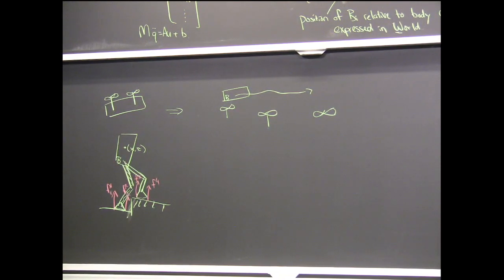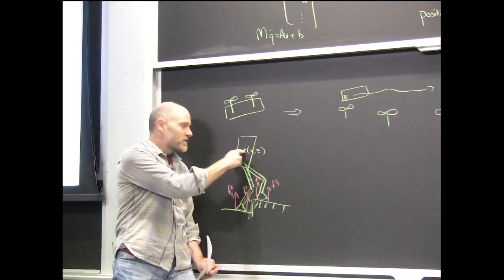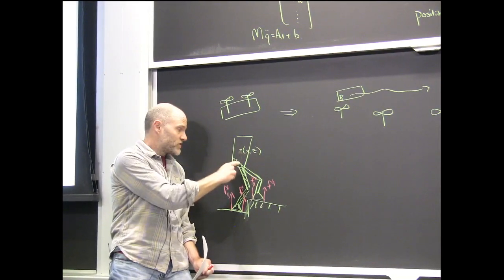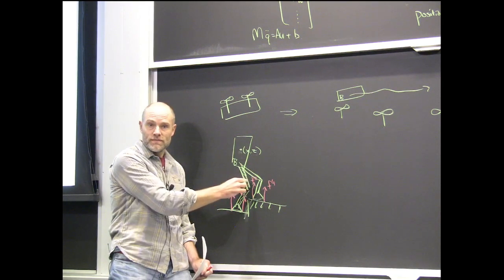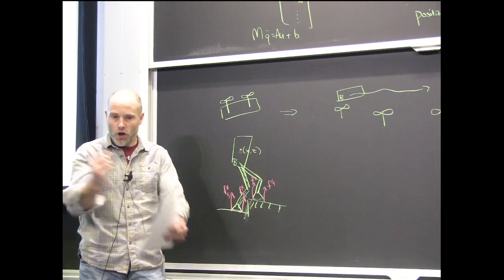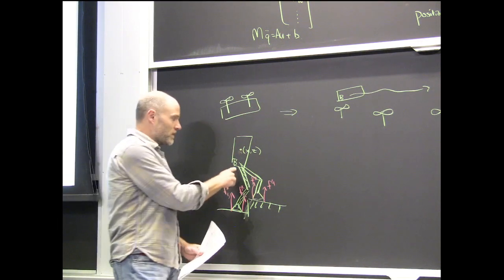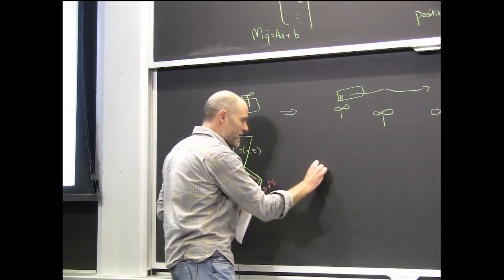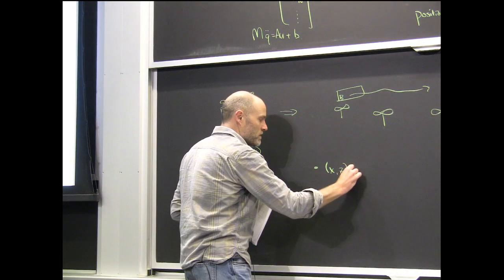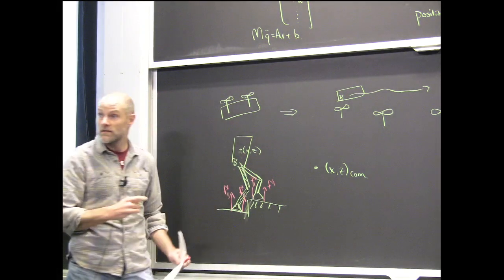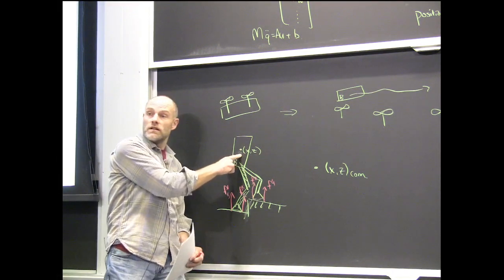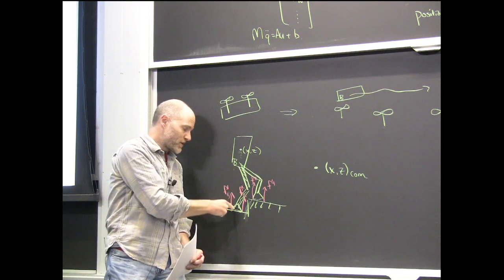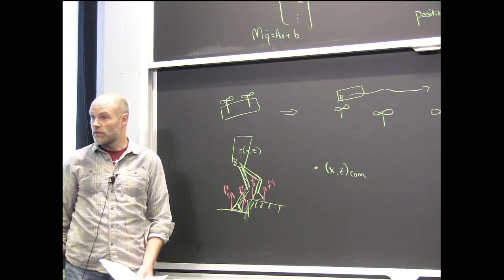And then the leap you want to make, okay, is that even if the legs have mass, the dynamics are still identical if I change this from being some fixed point on the body and now treat it as the center of mass of the multi-link system, right? The multi-link system can always be abstracted into a single center of mass that's moving through space. It might move relative to the torso, okay, but the dynamics are simple functions of those forces and gravity.